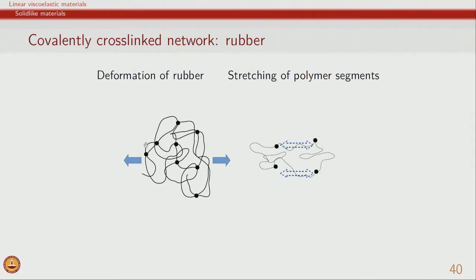If you look at the polymer segments, they look randomly distributed, just the way they would be in a solution or a melt. However, the polymer molecules are actually cross linked with each other, and these cross links are permanent and covalently bonded. So when a rubber like material which is cross linked covalently is heated at high temperatures, degradation processes will set in, but this material will not really melt because of these covalent bonds. And analogously, even if we take it to extremely low frequencies, or examine this material for extremely long times, no flow in the material is possible because of these covalent cross links.